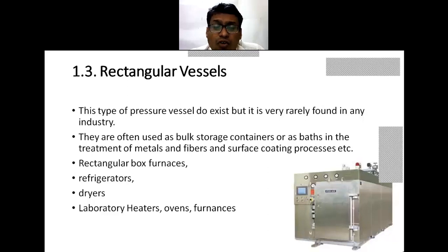Rectangular vessels are also easy for fabrication. Only the cutting and welding requirements are there. Bending is not required in the case of rectangular vessels. So fabrication of these rectangular vessels is even easier.